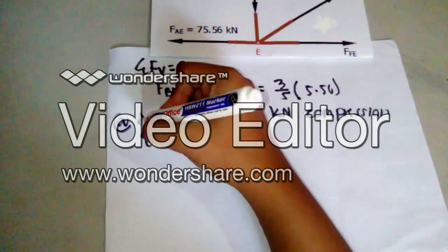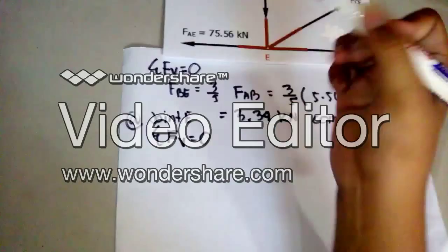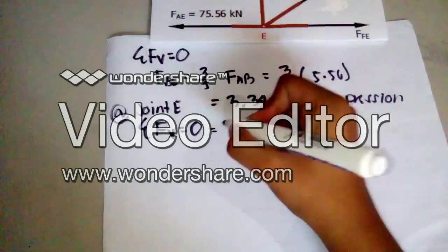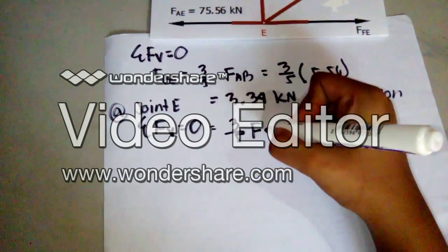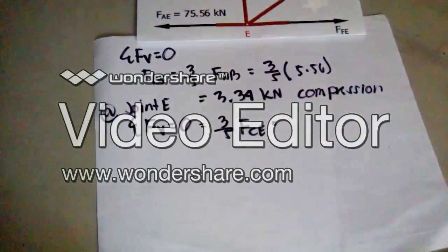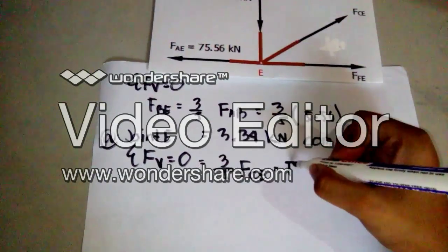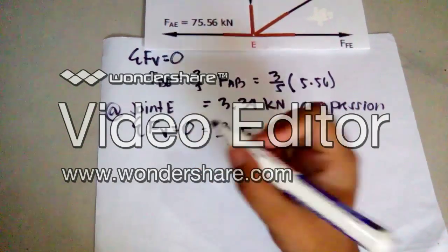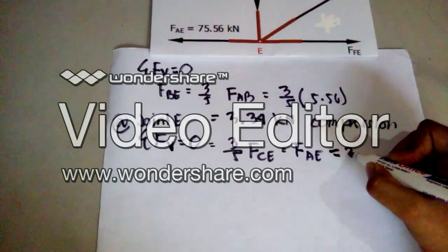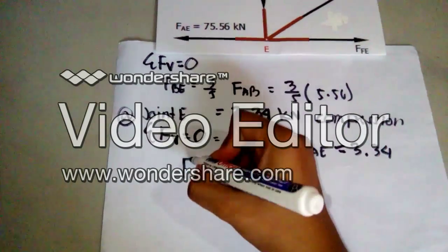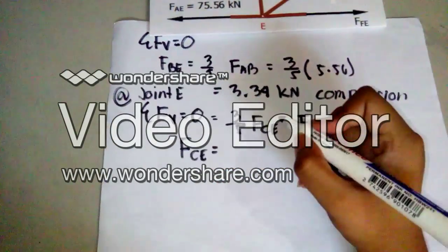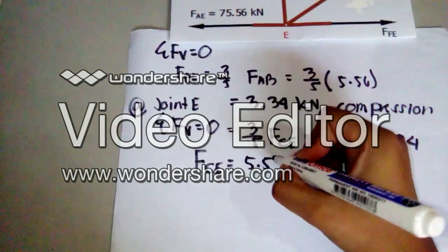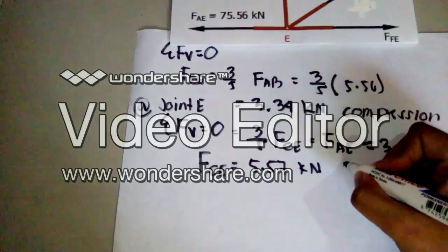We would divide it at joint E. 3/5 FCE is equal to FBE, which is equal to 3.34. So FCE is equal to 5.57 kilonewton tension.